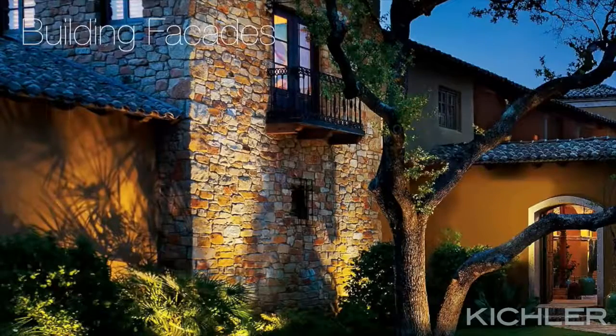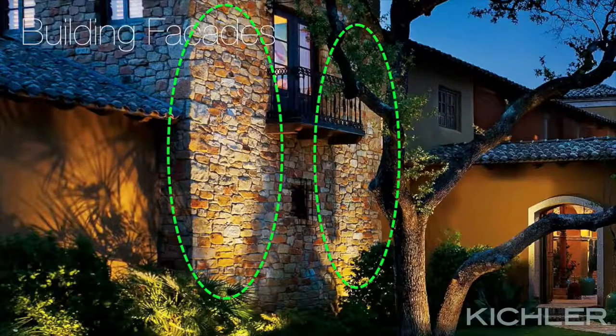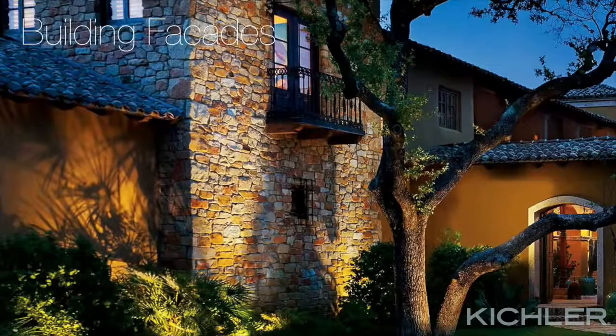The material of the building facade is perhaps the most significant determinant when specifying fixtures. Highly textured facades like stone, brick, stucco, or even some siding often do well with grazing effects, which are achieved by accent lights. Choose your beam spread based on the available space and consider the wall height when choosing a lumen output. Again, illuminance of about 1.5 foot candles at the top of the lit area is typically specified.